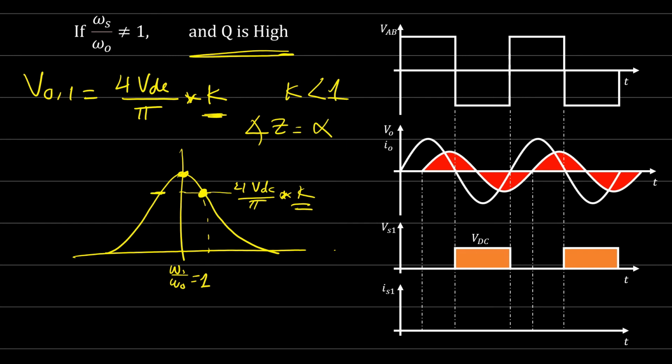By this we can control the output voltage, right? Because if we increase the frequency, we can operate at different values for the voltage. If you don't care about the frequency on the output, we can simply make a voltage control here. Sometimes we can underload our inverter and operate at this point, for example, and whenever we need, we can go upper until we get the maximum power, or the maximum voltage. So we can make voltage control here.